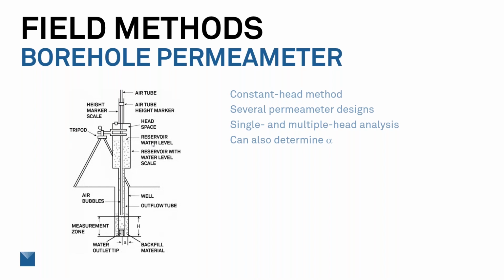Similar to the ring infiltrometers, you do have the ability to do the single or multiple ponded head analysis approach. With that multiple ponded head analysis approach, again, it allows you to do a better determination of that alpha value and helps simplify the three-dimensional flow corrections.